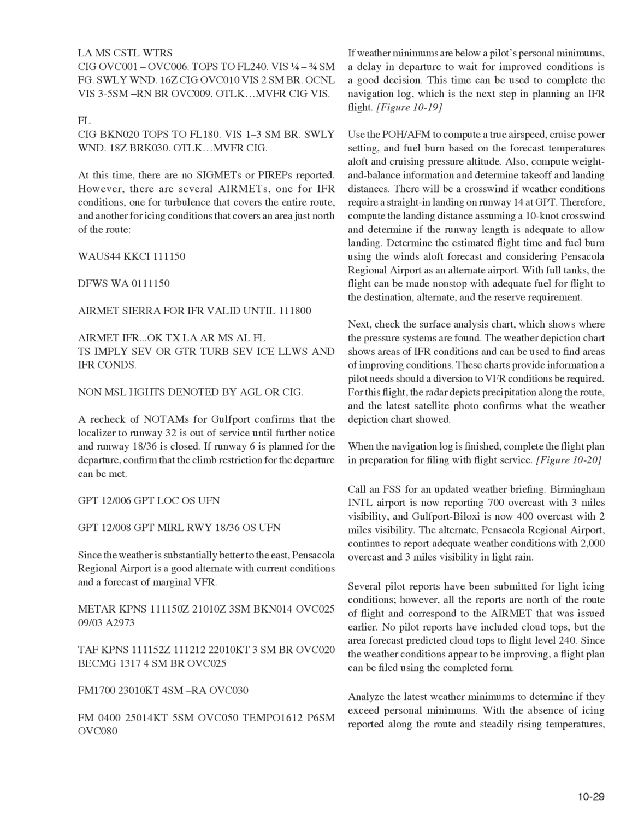Weather minimums are below a pilot's personal minimums. A delay in departure to wait for improved conditions is a good decision. This time can be used to complete the navigation log, which is the next step in planning an IFR flight.